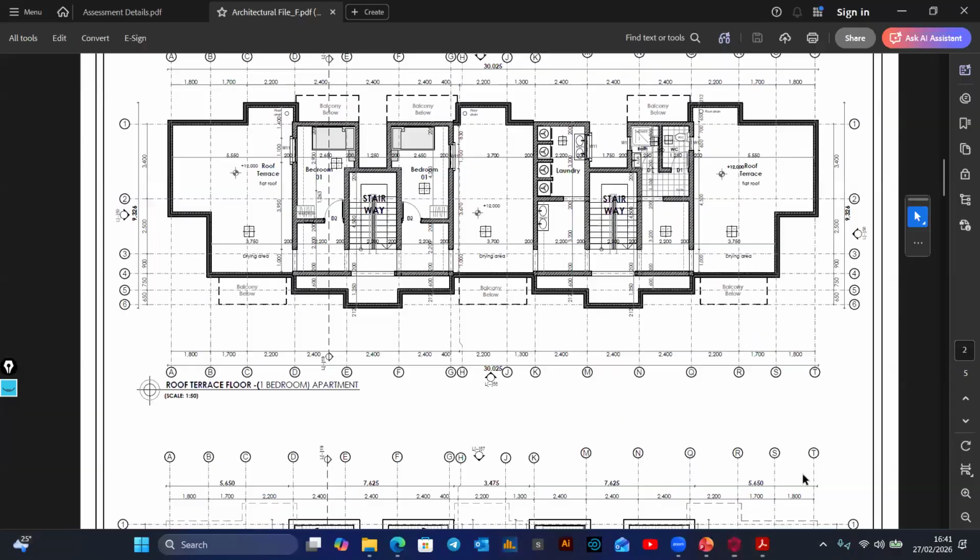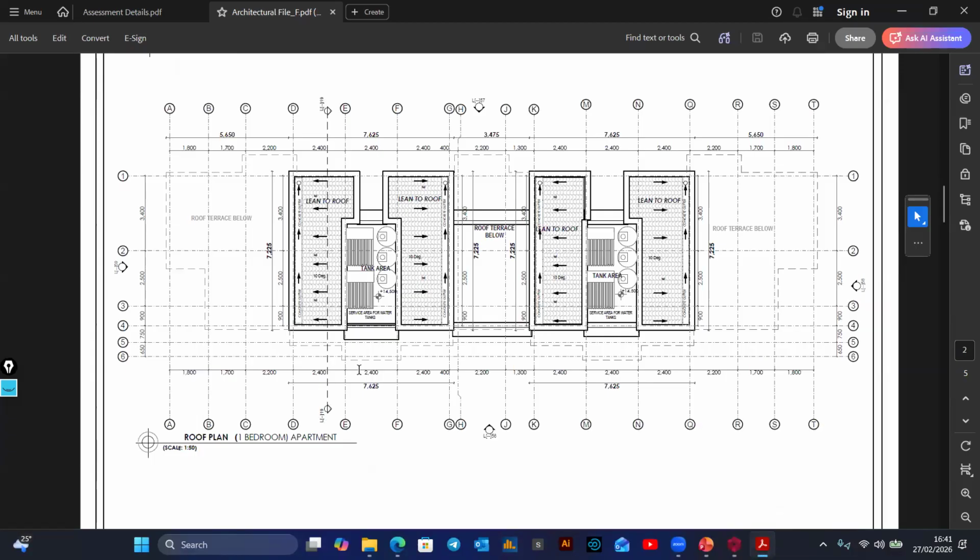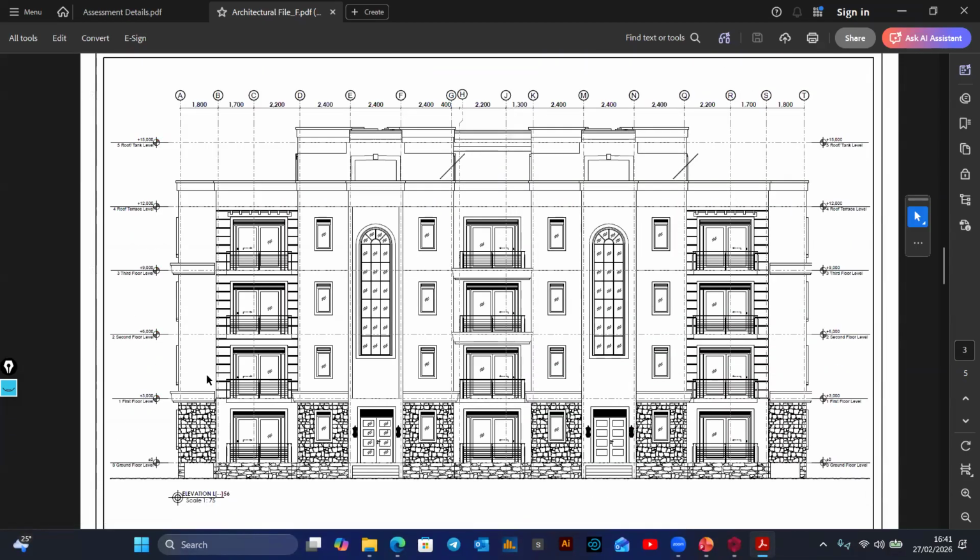If I look at the roof plan, I have the first floor, second floor, third floor, terrace, and then there are some parts inside which have a roof. So at this point, you have the ring beams. The water tanks are going to be placed at that level. Where you have the ring beam level, that's where you shall have the water tank slabs. Get it? Yes.